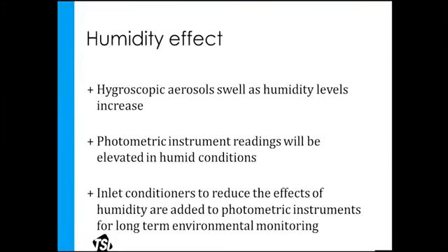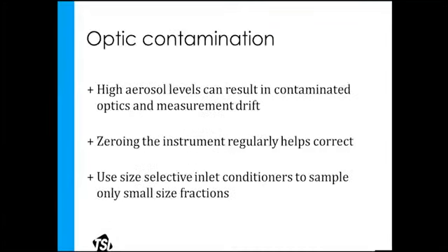It might be dry in Arizona, or it might be moist up in Seattle, and so that filter paper will collect the aerosol and will collect moisture in the air. So you'll bring it back to the lab. The lab will, again, let it normalize for 24 hours in that humidity chamber at that same temp, that same humidity it started. So it normalizes. Extra moisture will dry out. If it's too light, it'll come back. So we do that with sampling data anyway. So conditioning for humidity is done with sample data as well as gravimetric data. We just have an extra option there, a tool added to the instrument to help do that.